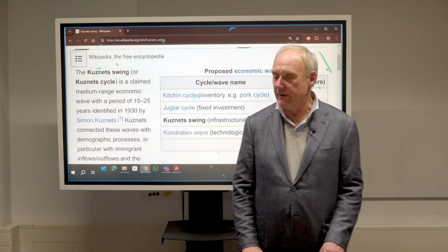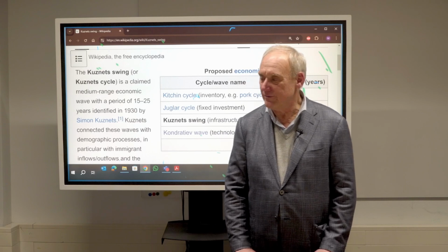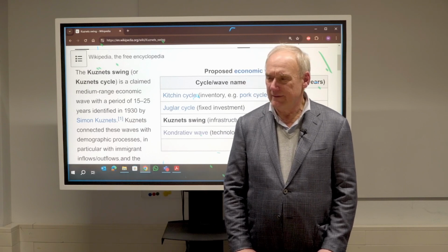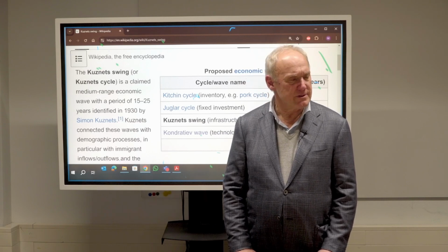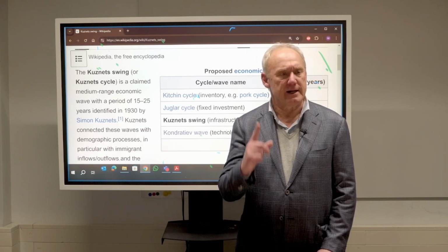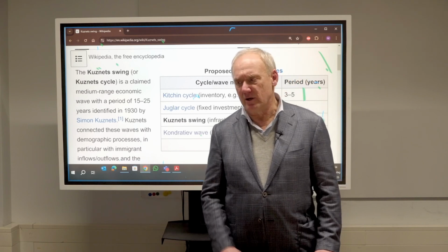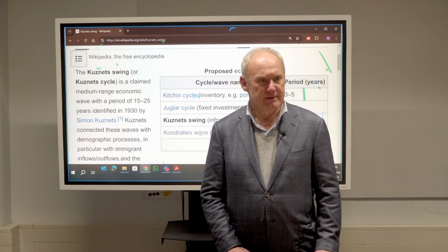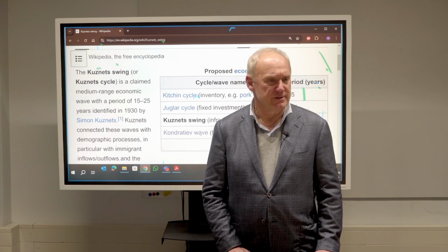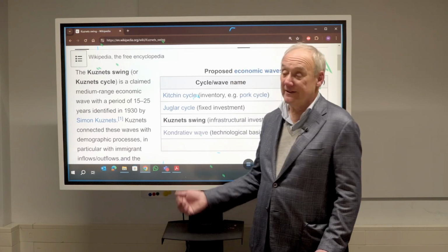What's the order of that model, your system? 4 cycles. What order is it, 8 or something? I always forget. A second order model has 1 cycle, right? 2 poles, but they're conjugate, right? So for 4 cycles, you need an 8th order model, right? Yeah, that's it. There you go.